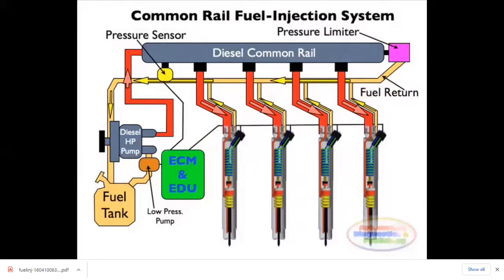Pressure energy is stored remotely, and the injectors are electrically actuated. The injection pressure at the start and end of injection is the same pressure in the accumulator, thus producing a square injection pattern. In other words, the injection pressure and rate will be the same for each of the multiple injection events.